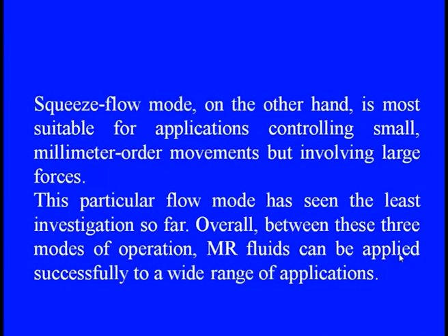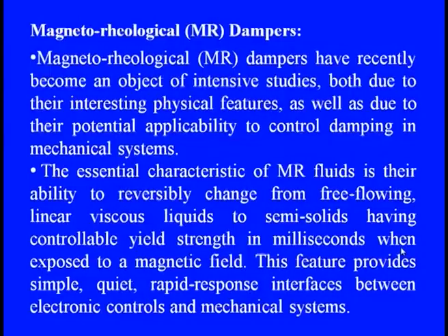So MR fluid can be applied successfully to a wide range of applications according to the service condition and applied features, where we want to control vibration or excitation. As far as the vibration control problem is concerned, they can act as dampers. MR dampers have been the object of intensive studies, both for their interesting physical features and for their potential applications to control damping in mechanical systems.